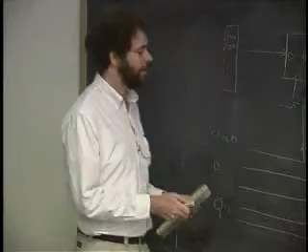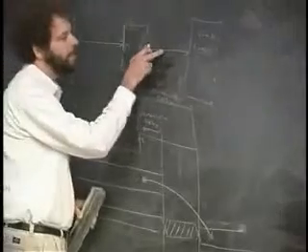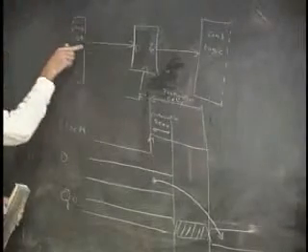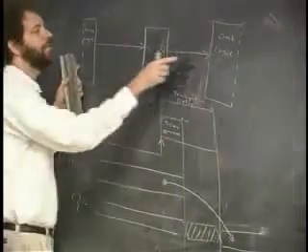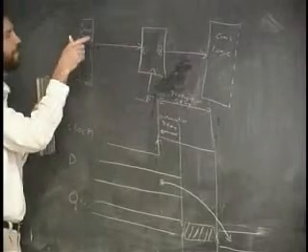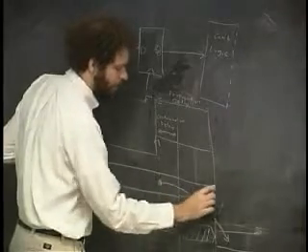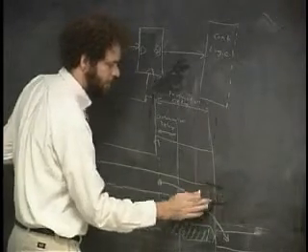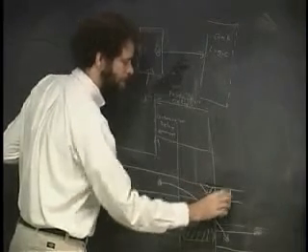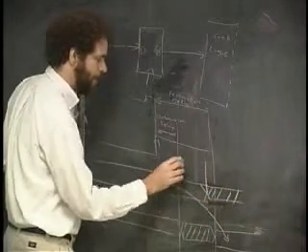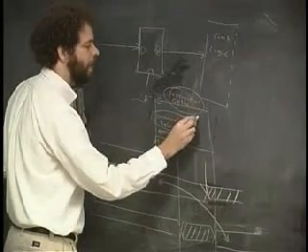Okay. Now, after the output Q gets contaminated, that contamination begins to filter through the combinational logic over here. And so a delay through here, which is actually the contamination delay of the combinational logic, is the time it takes for the contamination to hit here. And so this also gets contaminated a short time after that. And so let me write that kind of like this. And so at the time from here to here, this is the contamination delay and propagation delay of the flip-flop.